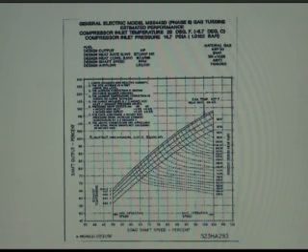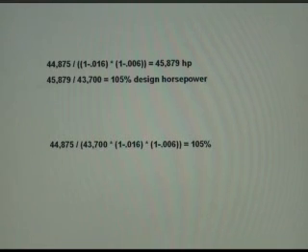And then the second thing that you would have to do was to convert either the ISO rated power of 43.7 to the site rated power, which would be with your inlet and exhaust losses, so you'd subtract 2.2%, or you would change the horsepower that I gave you to an ISO, semi-ISO condition by adding 2.2% to discount the losses in the inlet and exhaust. So that would give you a horsepower that you could compare.